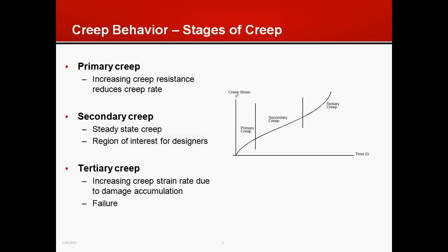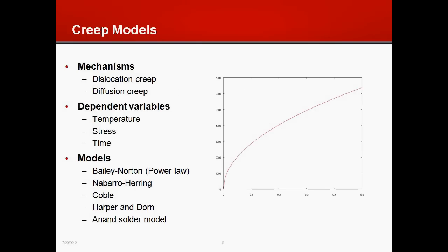This curve can also depend both on temperature and the stress level that is experienced by the part. Here I do not show all the dependencies, but for higher stresses or higher temperatures, you may have to plot different curves. So there are multiple mechanisms of creep that can come into play depending on the specific material and the loads and temperatures experienced by the structure.